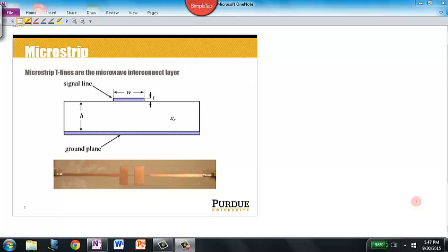Instead, they're almost always constructed out of small, flat circuit boards that use microstrip transmission lines as the interconnect layer. In fact, the parasitic behavior of wires will often dominate circuit behavior, meaning that it is actually physically impossible to get microwave circuits to work appropriately if you were to try to breadboard them.